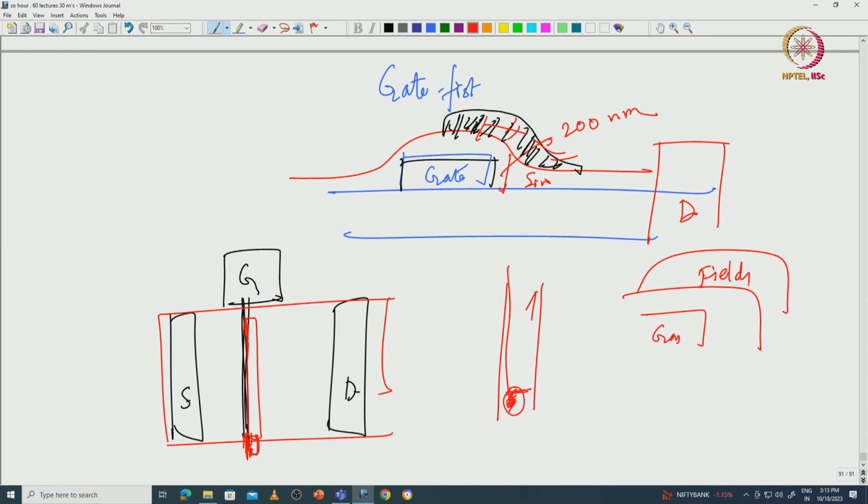So, the field plate metal could be nickel gold, for instance. It is going over the gate, but it is metallically shorting the gate outside the mesa, maybe here you are shorting, or maybe you can short here. So this is a gate connected field plate, you etch and do it, but then this is a gate first, but you can do even gate last or gate second. I am talking about only in the context of silicon nitride passivation.